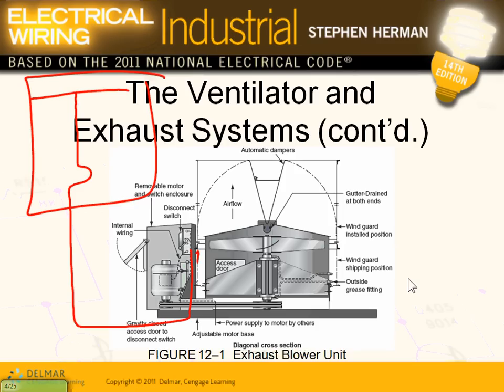That's my interface. Most of the time, this one, guys, comes with the equipment, a disconnect with the equipment. Otherwise, you have to provide the disconnect right next to the air handling unit, an overcurrent protection device, and a feeder. And Nick, if I tell you this baby here is running at 15 horsepower, 480 volt system, can you size the feeder and the overcurrent protection device for it? If you can't, ask for a refund from Dunwoody right now.